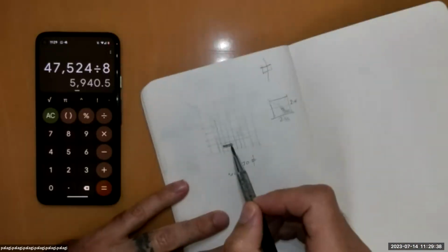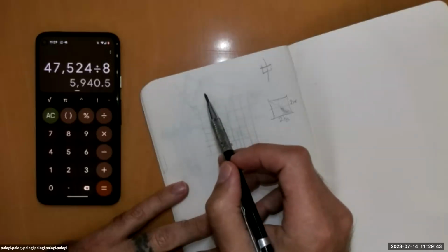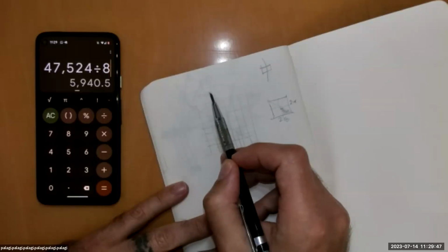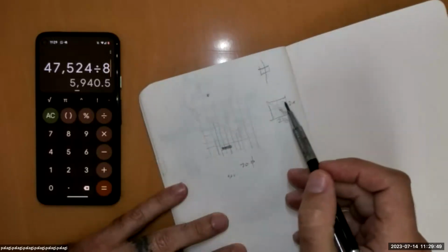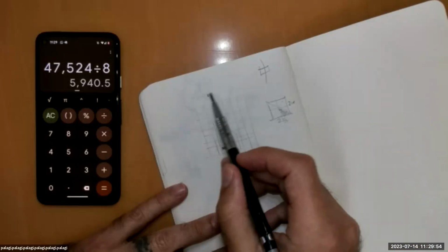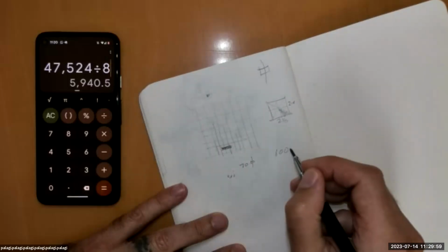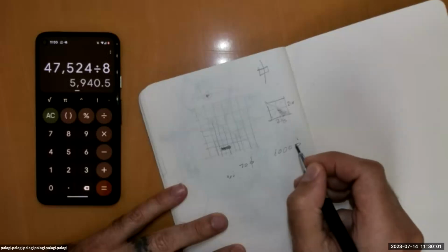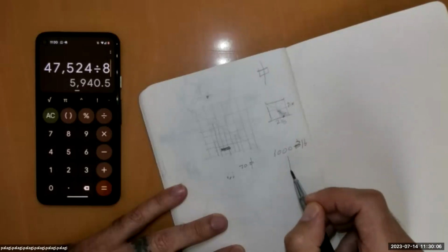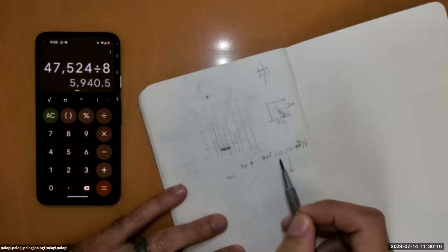So the logic was, we took the weight per linear foot of that I-beam and averaged it over its tributary space to get an average per square foot for the top plane. We took the whole area of the building, figured out what proportion that column is handling, and multiplied. Now that's the weight. We've got about 6,000 pounds going down for that column, for just those WWF beams.